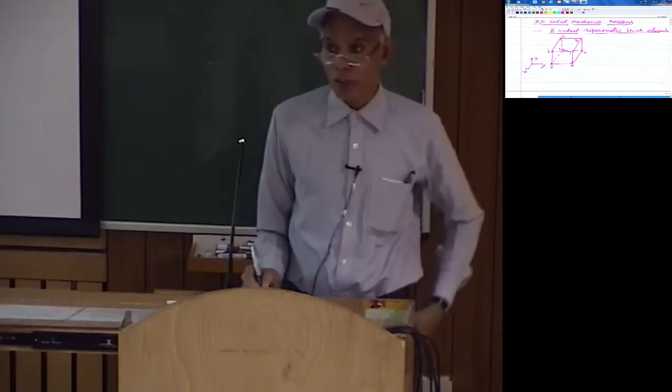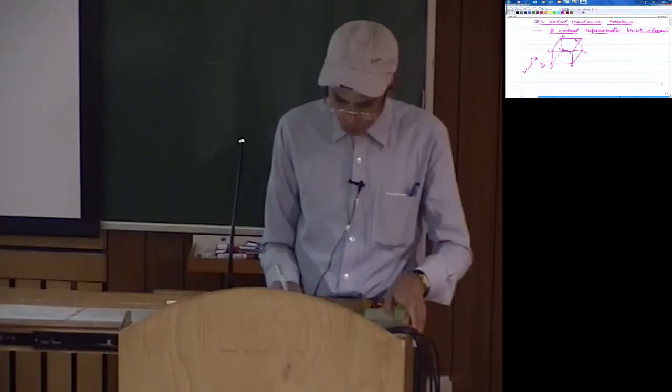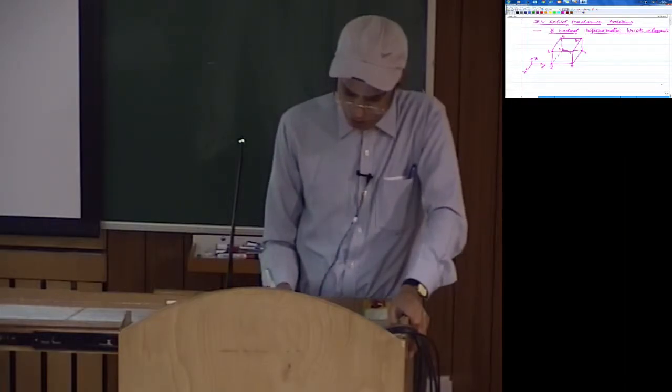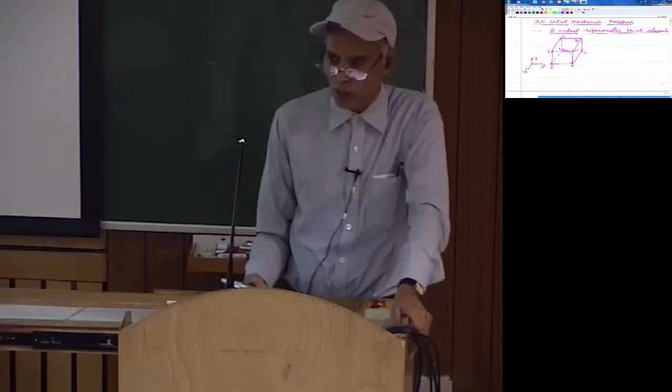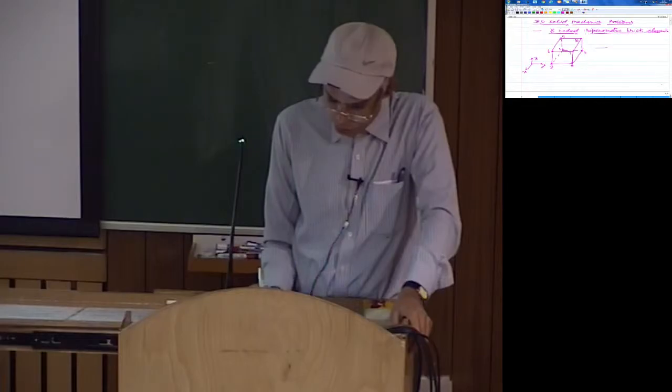And you can always deduce a tetrahedron from this by, say, if you collapse all the top 4 nodes, 5, 6, 7 and 8, into 1, and maybe any 2 nodes on the bottom face, that is 1 or 4 or 3 or 4, you get a tetrahedron. So this is the element in the physical coordinate space, and then we map this to the natural coordinate space.